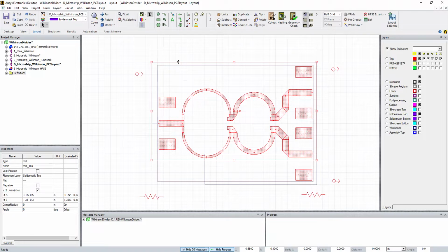So imagine that I'm filling this box with the lack of solder mask, because the board shop actually does a negative. So there's going to be no solder mask here, and then I put another box right here, and there's going to be no solder mask there, which means the only place on the top layer that there's going to be solder mask is this little corner down here, because I haven't done anything there.